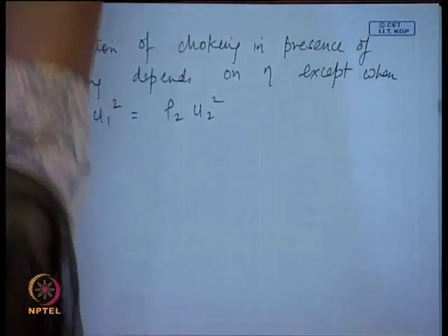So, now I would like to deal with another type of very simple situation. See, whenever we find that the two phases are accelerating through a nozzle, even for a single phase accelerating through a nozzle. We have a good amount of fluid in say any particular stationary tank, and then we have a nozzle connected to this. So, the fluid flows through the nozzle, a converging type of nozzle. Now, for that particular situation, which are going to be the dominating forces? Normally, the forces we have are gravitational forces, frictional forces and acceleration pressure gradient, isn't it?